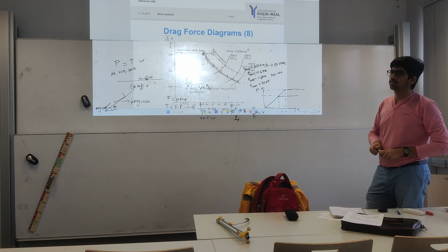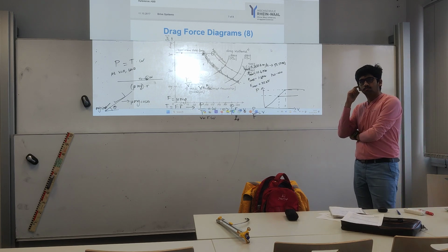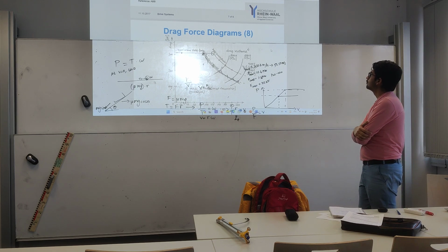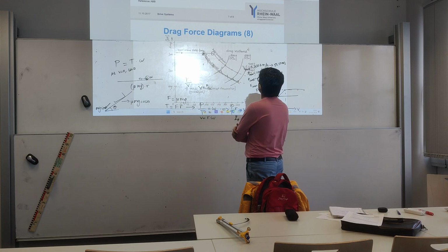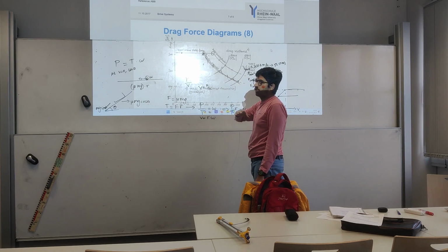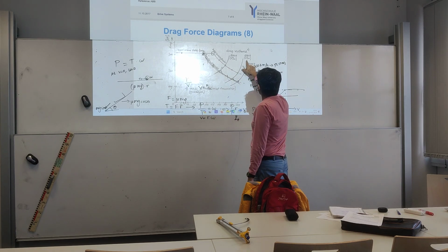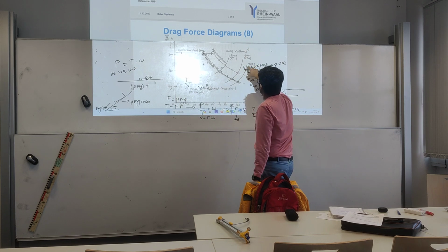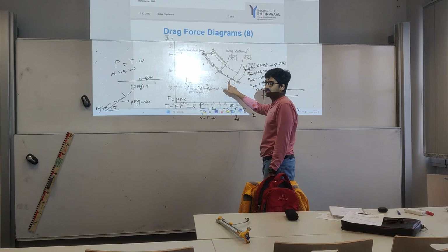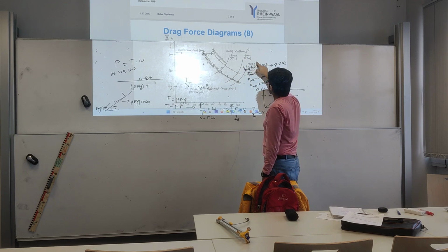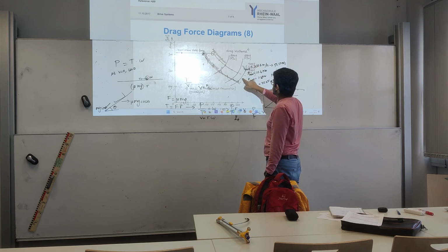Clear? Yeah, that makes sense. But now my question was, what are these like 800 and then what are these gradients? The resistive gradients, the drag resistance. So that is basically this zero gradient. It means it's on flat terrain. This is also flat, but lower. So that's the limit basically. Here it's having a lower mass, 600 tons, so it can go faster. Here it's even lower, 400 tons, so it can go even faster.